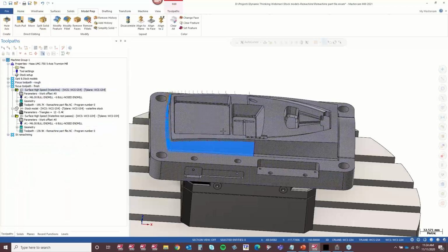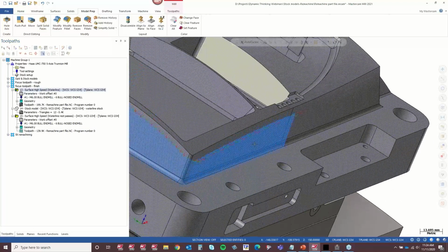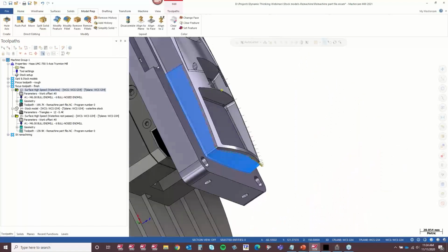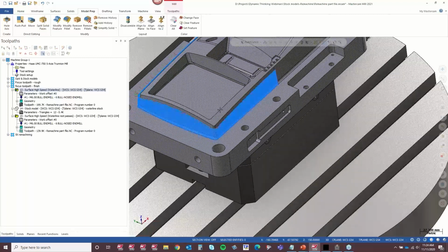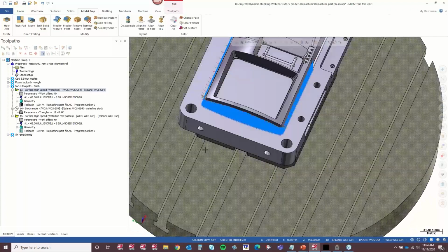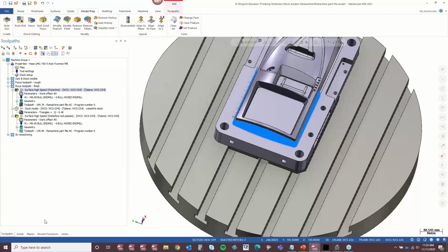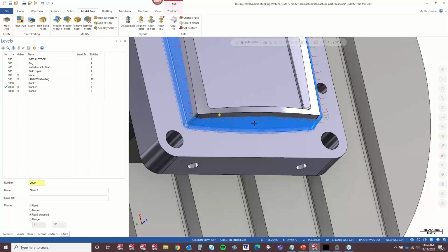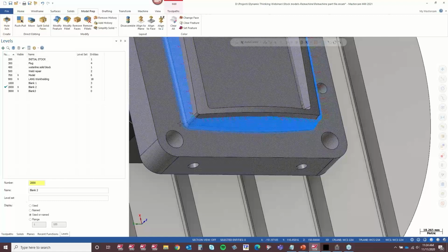And I just want to show you, so typical waterline toolpath, I've selected the surfaces coming all the way around the outside of this part. You can see the break in the surfaces. We're doing this whole edge. Now I can do something very similar to what I did with that roughing operation. I can come in and say, all right, I want to create a chunk of material to trim that waterline out, right? And maybe I'm only worried about this corner, okay?